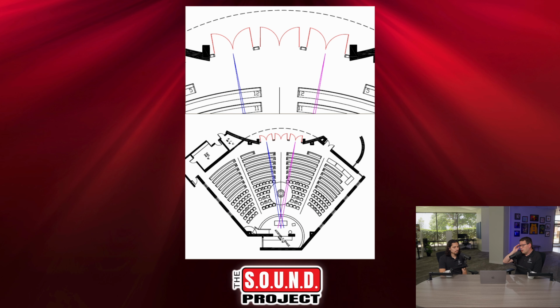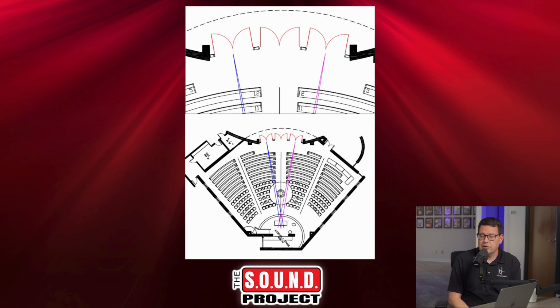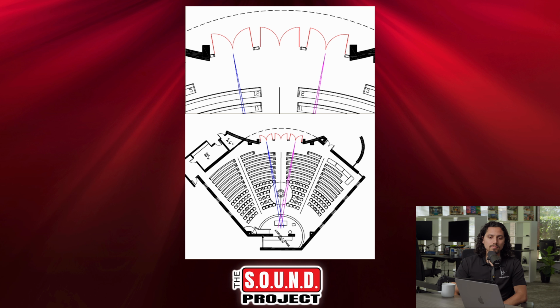One of the other things that we caught early on in the design process is that the back wall originally had kind of a concave surface where those entrance doors were. And those entrance doors were mostly glass, so it wasn't something that we could treat with acoustical panels. So in the design, instead of having a concave surface, we just flattened it out. You can kind of see on this that sound generated from the stage would get focused right back to the stage because the center of the radius of curvature of that back wall just focused in on that stage area. So we were able to avoid that just by making a little minor change to the doors.